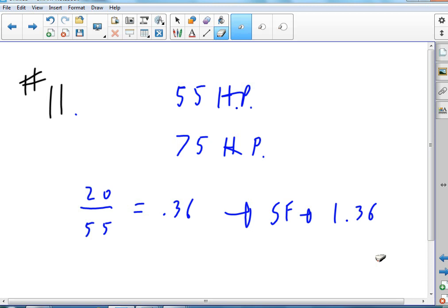So in a nuclear power plant, it's typical to have design margins of 2. So the plant is going to 1,600 pounds per square inch. That's its normal operating pressure, but it's not going to break if you went twice as much. So it could go to 3,200 pounds per square inch and not break. That's the design margin.